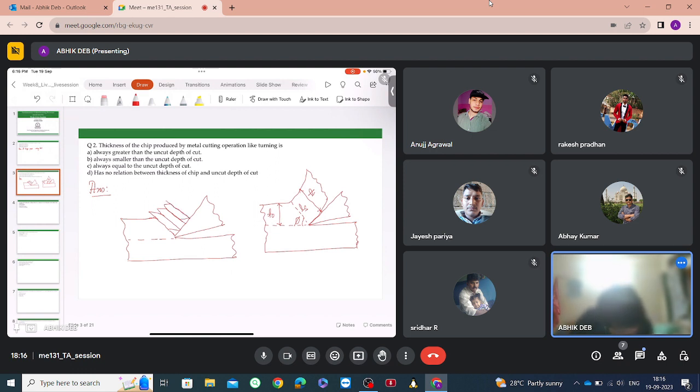Okay, so this is how the shearing will happen in this direction. So on the application of shear force, the grains tend to get elongated, or deformed, in a direction along the shear plane. As a result, from this side, a grain which is like this will start becoming elongated along the shear plane.